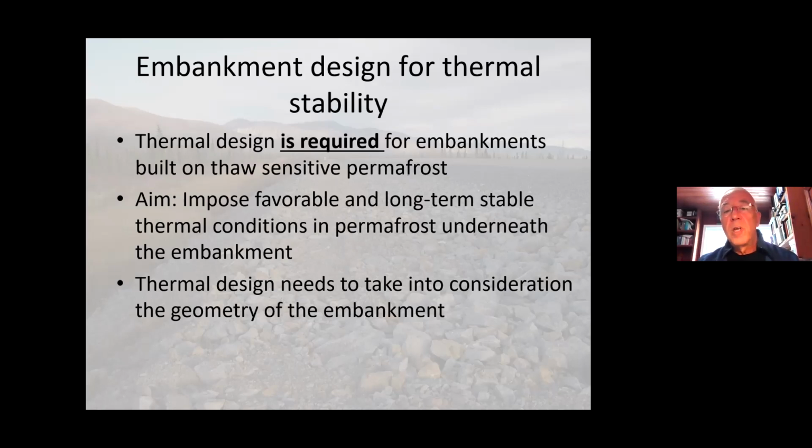Thermal design needs to take into consideration the geometry of the embankment. In my old days, when I was working in Nunavik for the design of airstrips, we were only investigating the center line of the airstrip, and we're assuming that if we're maintaining good condition under the center line, if we're raising the permafrost level, the airstrip would be stable forever.